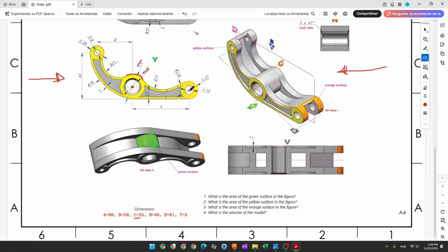Now let's create these 2 circles here. One with 12 millimeters of diameter and the other with 25 millimeters of diameter. And the distance between these 2 points here is 8 millimeters. And we have this line here that is tangent with both circles. And this point here is vertical with this point, okay? And the same on this side.